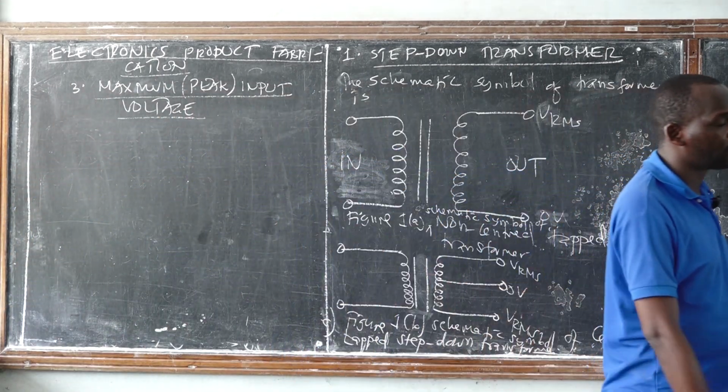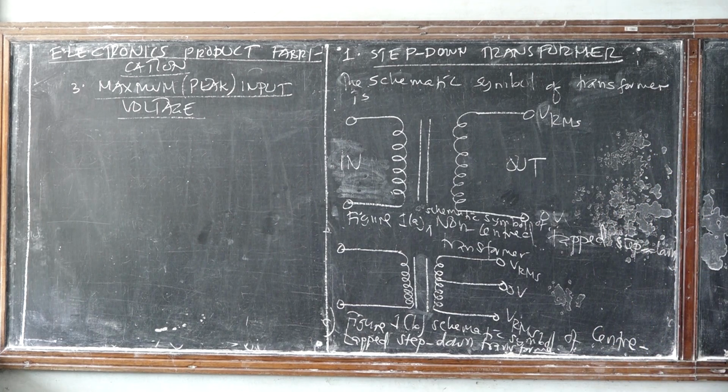Some simulation software doesn't give you access to feed the root mean square voltage, because 220 volt to 240 volt is root mean square voltage. Some simulation software lets you feed the amplitude, which is what we call the maximum or peak voltage. During simulations, I will show you.